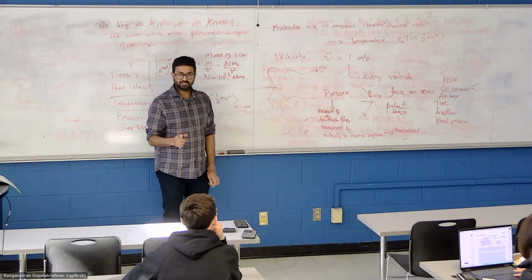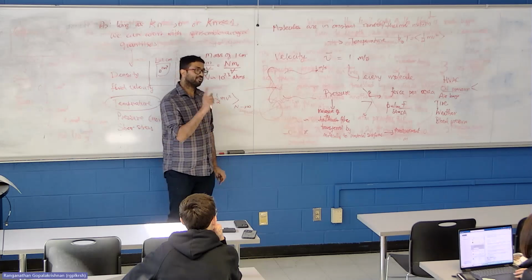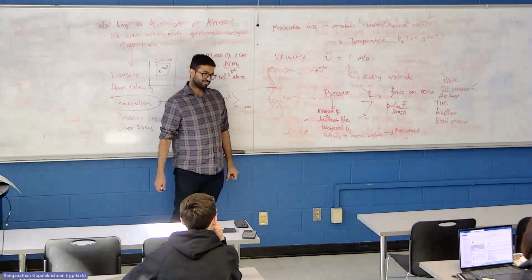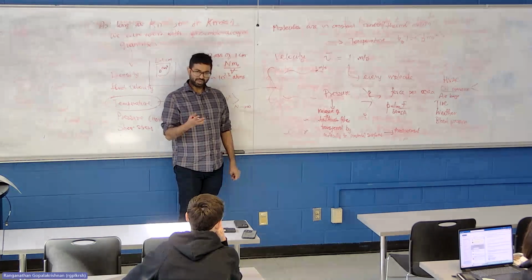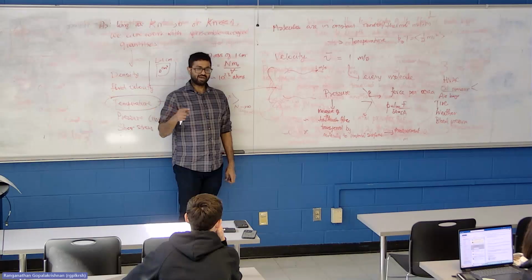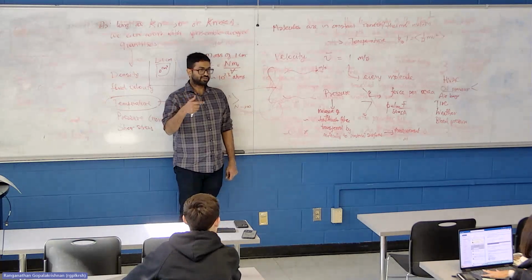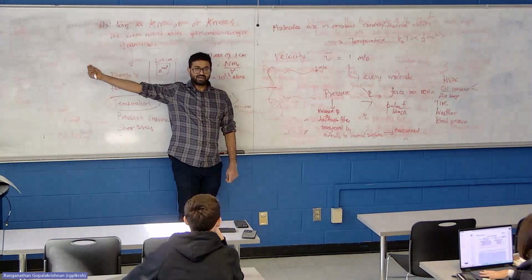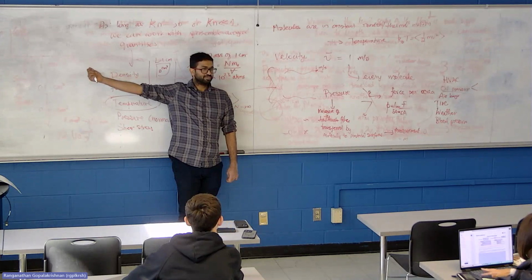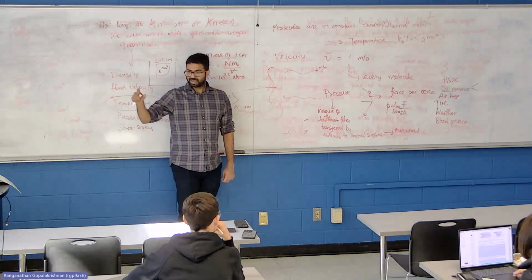One more example. I'll let you go. Using a pressure washer. I'm asking when do you measure pressure in your home? Residential units may not have this, but most commercial buildings will have a pressure gauge at the water inlet, so that they check whether the city is sending the water at the specified pressure or if there's a drop in pressure. If you go to facilities management, just walk in and tell them you are a student, you just want to know how pressure is measured. Look at the pressure gauges for water. They may even have one for the gas utility, the gas pressure.